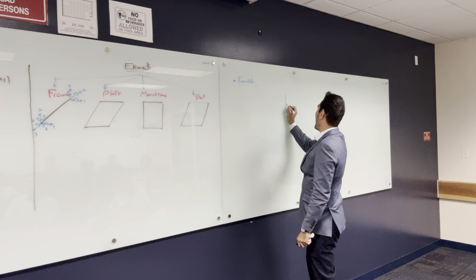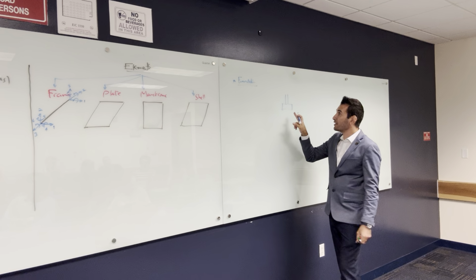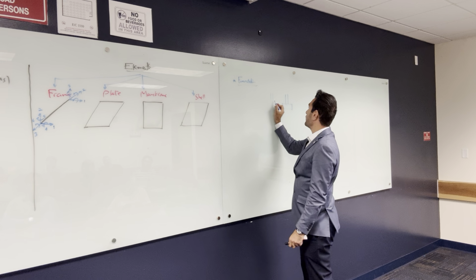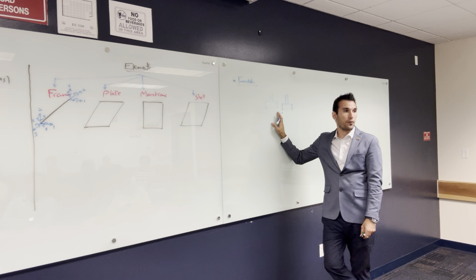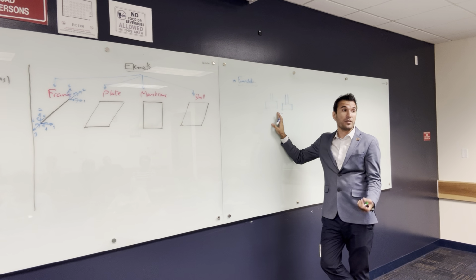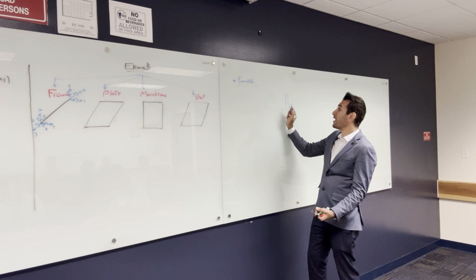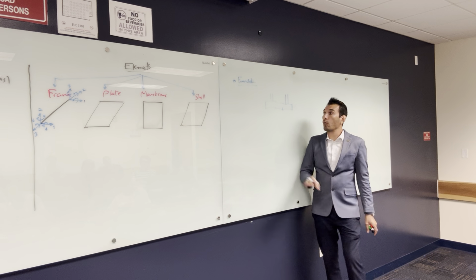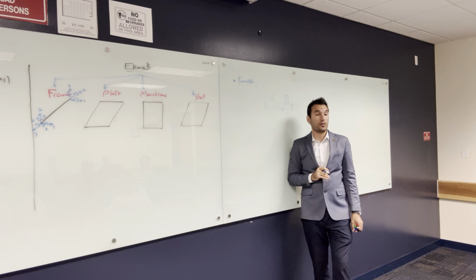All right, so if I have a single column, I can make something like this, a footing. And we designed the footing to take this load. So what if I have a column very close to this one, and I assume that at first it can be an isolated footing, but when I designed the foundation, I found that the load is very, very big, and this foundation needs to get bigger, and when I got the foundation bigger, it intersects with this one. So we combine them together. We make a combined footing, so that's another one.